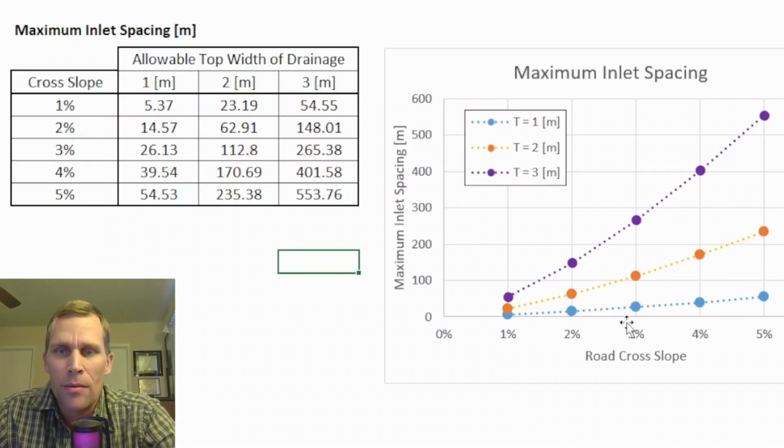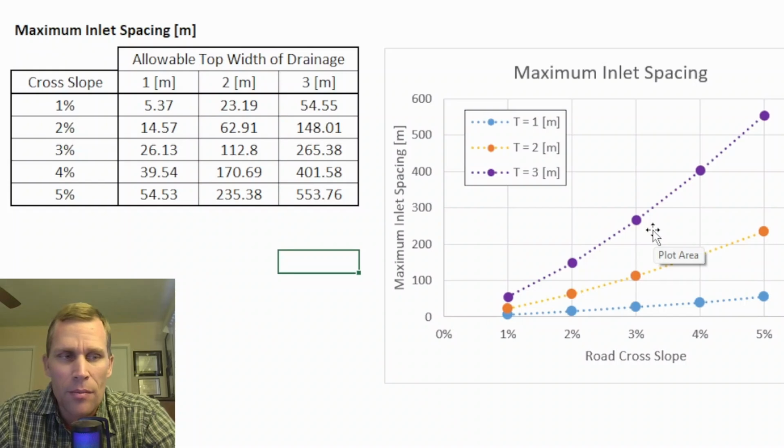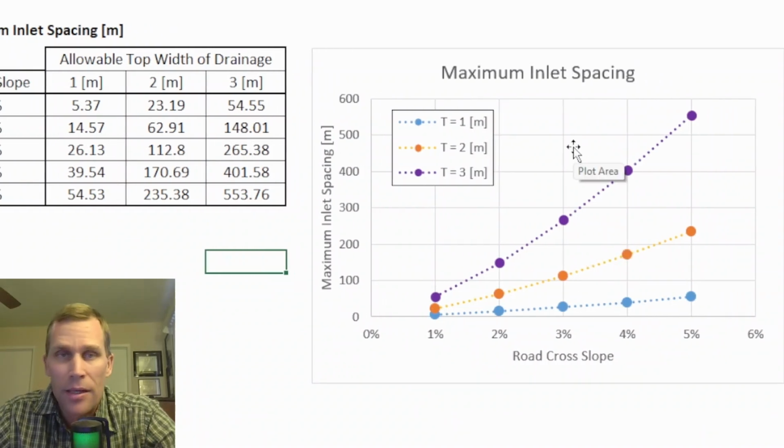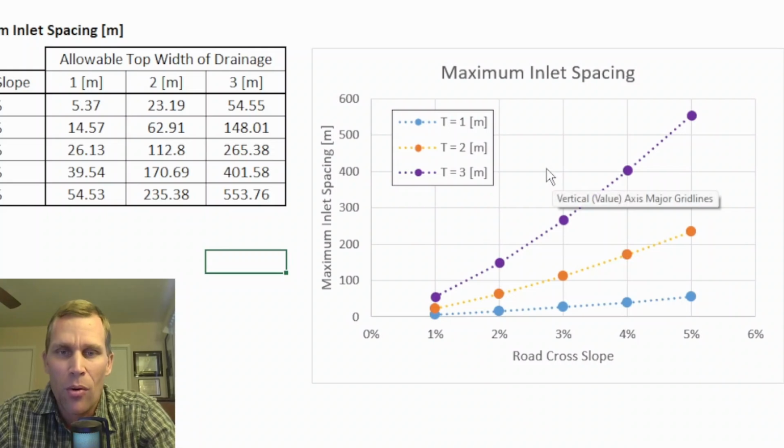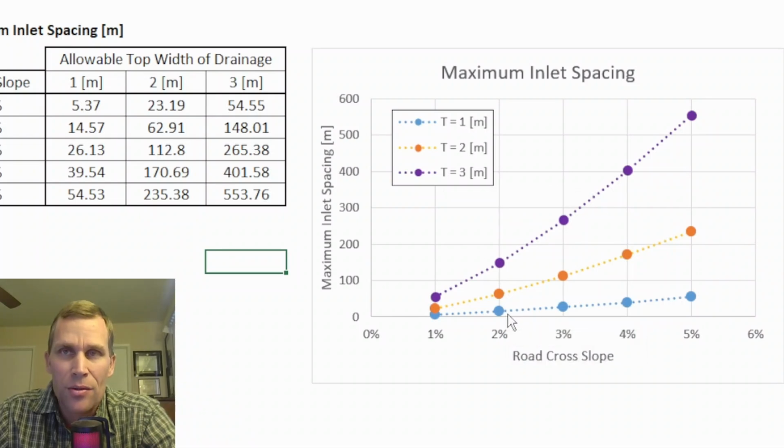Now, this particular plot is specific to our data. Remember, we had some 89 millimeters per hour, a runoff coefficient of 0.9, and also the Manning's n coefficient for roughness. So this data could actually apply to a specific location on planet Earth. It could be the 300 block of Park Street. This plot could go into a report. So even though we're using this specific data to look at general trends, it also corresponds to our specific case for the input data that we provided.